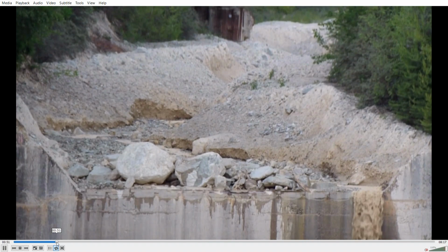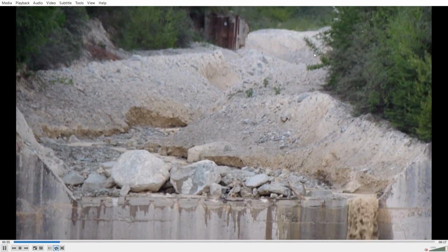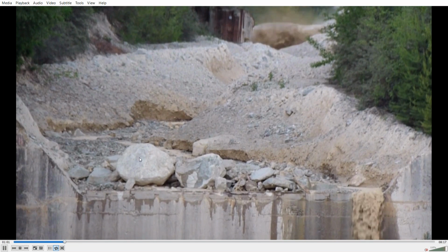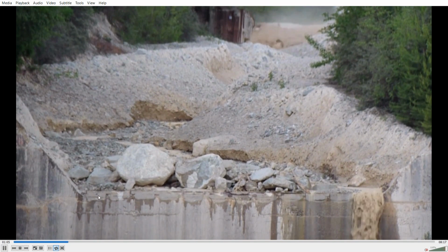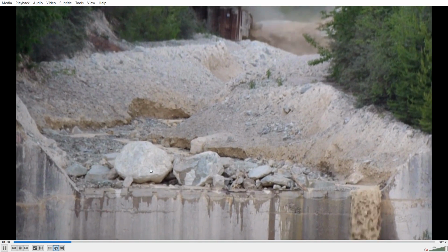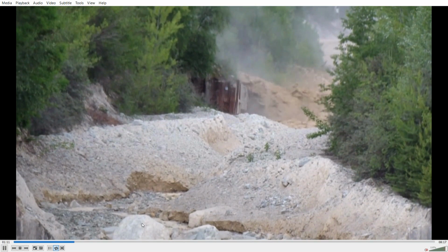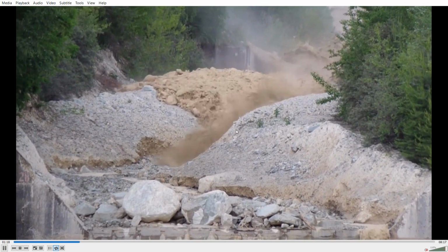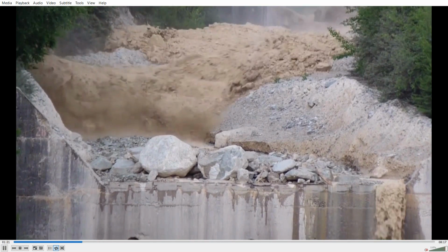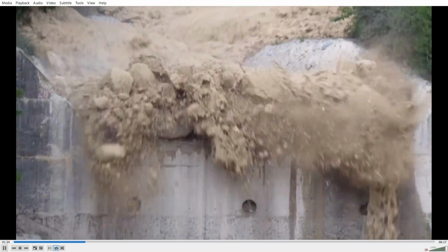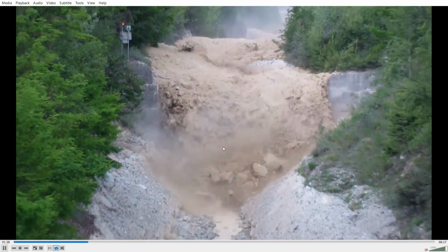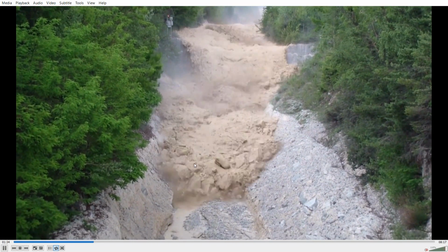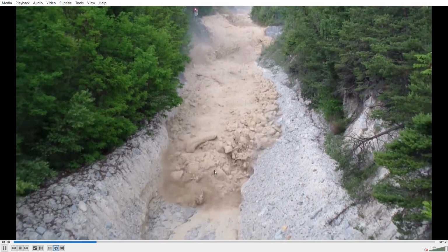And I want you to note the arrival of the flood wave is going to have a bouldery front, maybe some debris, and it's going to go over, here it comes, and it's going to go over this Sabo Dam type of works here and lift these boulders off, and these will become part of the frontal wave. So here comes the frontal wave, and you'll see that it's moving a little slower than once the peak arrives. And that's because of both the interaction with the friction in the frontal wave and the fact that these boulders are kind of holding the flow back a little bit.